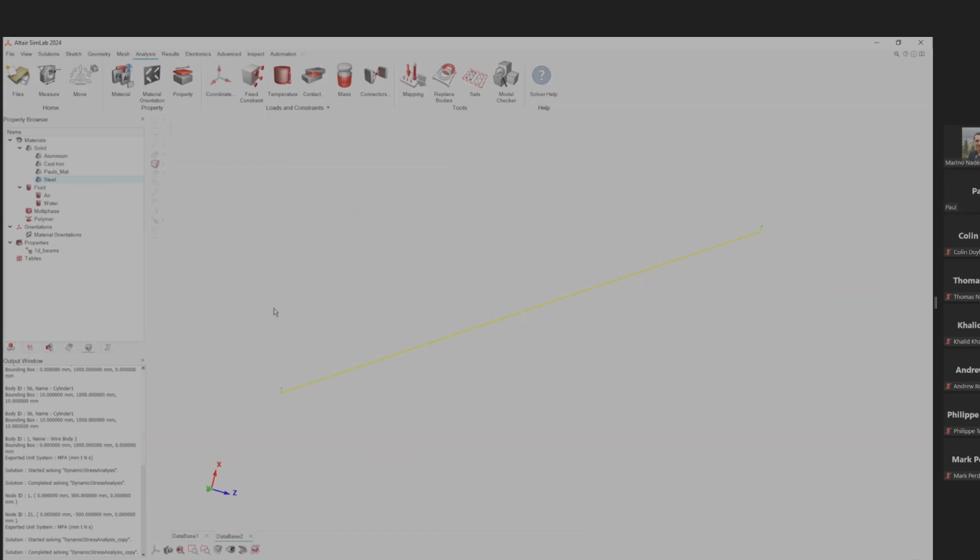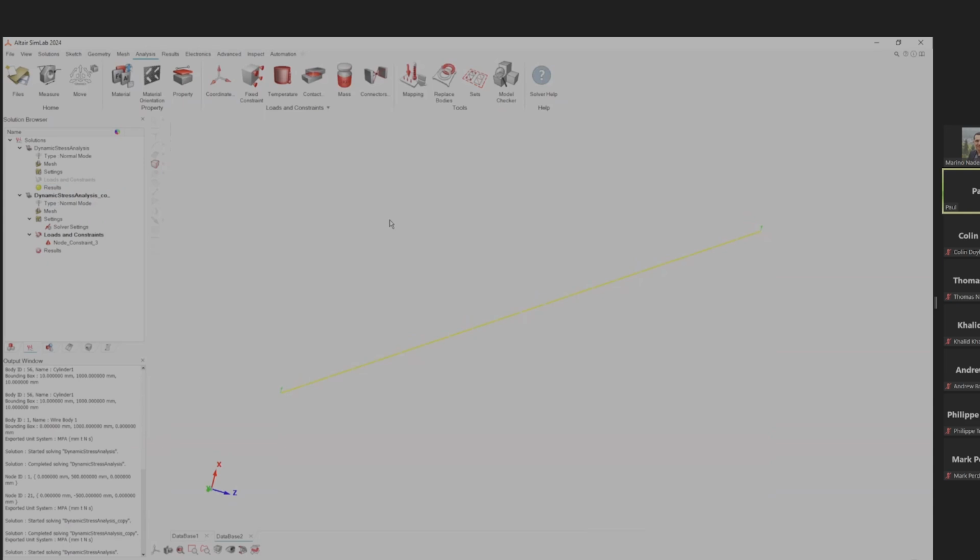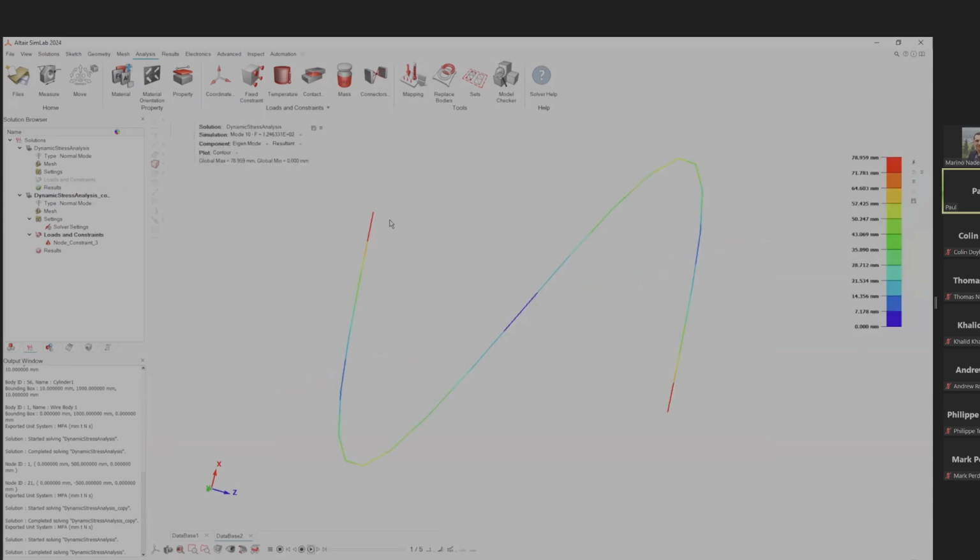And what about seeing the frequencies once the damping properties are applied? Let's say I were to right click and update this. So let me rerun the solution. Okay, it's done already. So all my frequencies here, let me see, is there a way you can get a table of them? I don't believe so. So all my frequencies are listed out here.